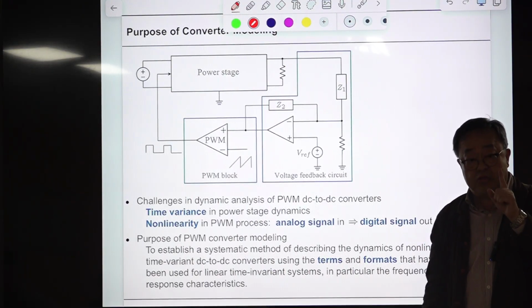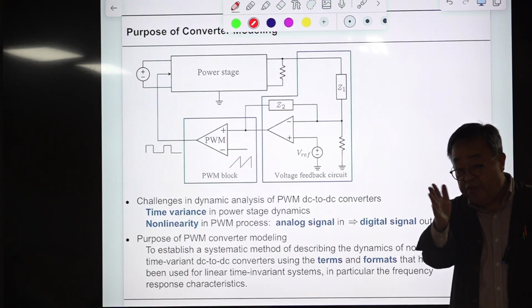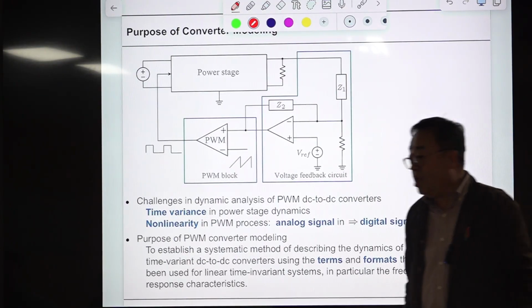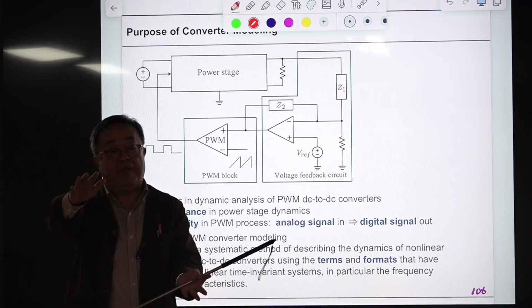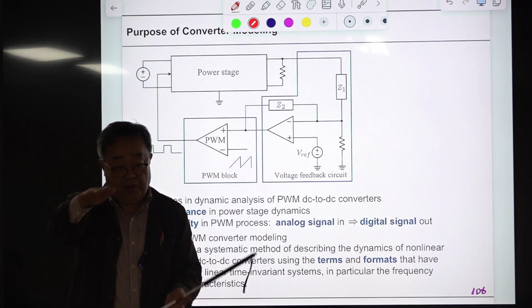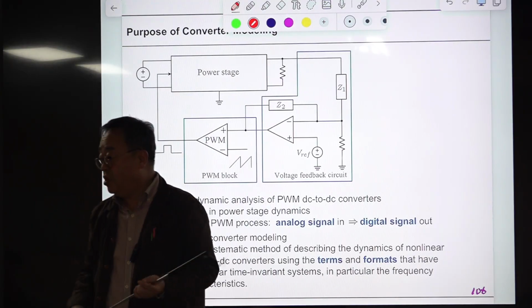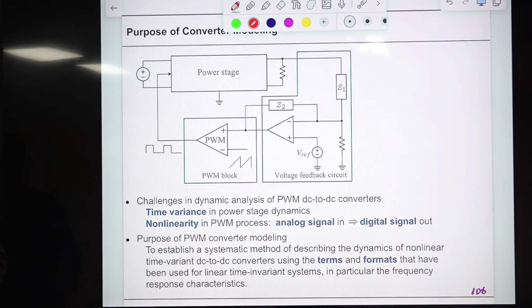So the first assumption is a small variation in the operating point, and the other one is the small signal assumption: the AC component is much smaller than the DC component. That assumption is also used in electronics when you derive the small signal model of a BJT amplifier. You are not thinking about the BJT itself. You are using the equivalent circuit, pi model, T model, something like that. The same concept is here.